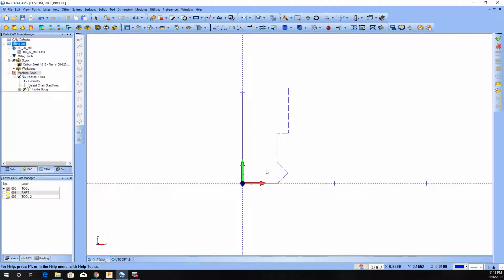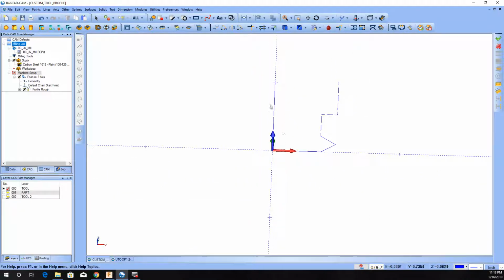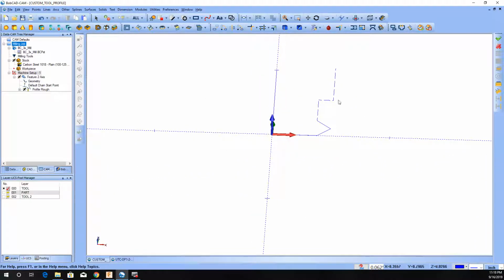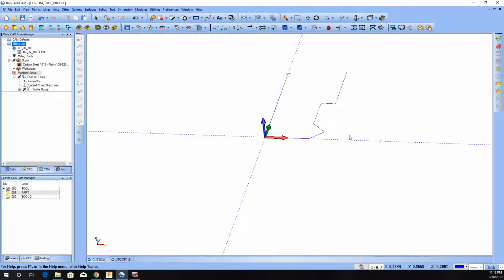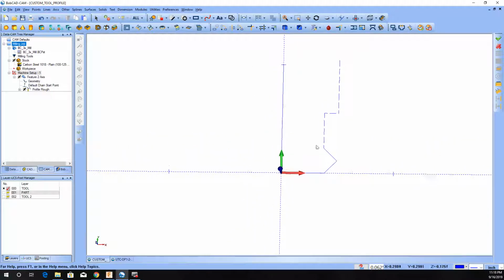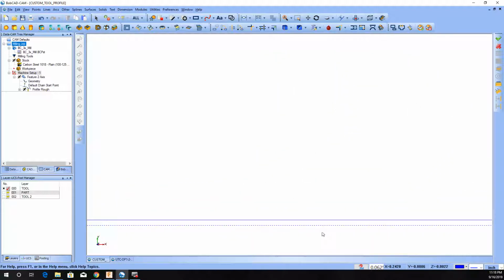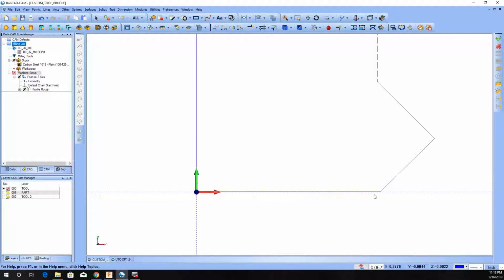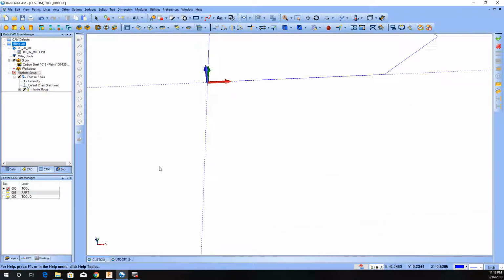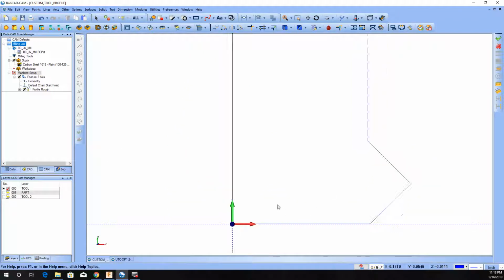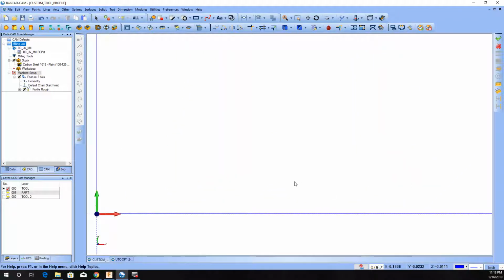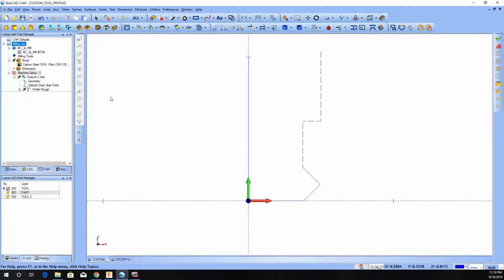For the diameter of the tool, you basically want to draw it to where it'll essentially be spun around this axis. It'll revolve around the Y to generate the diameter, and I think I'm maybe a half thou off this axis, but you want it to be there, so it's going to spin around the Y for diameter. It's going to sit along the X for the height of the tool, essentially. Dotted lines will be essentially representing the shank of the tool, and I'll show you where to set that up.